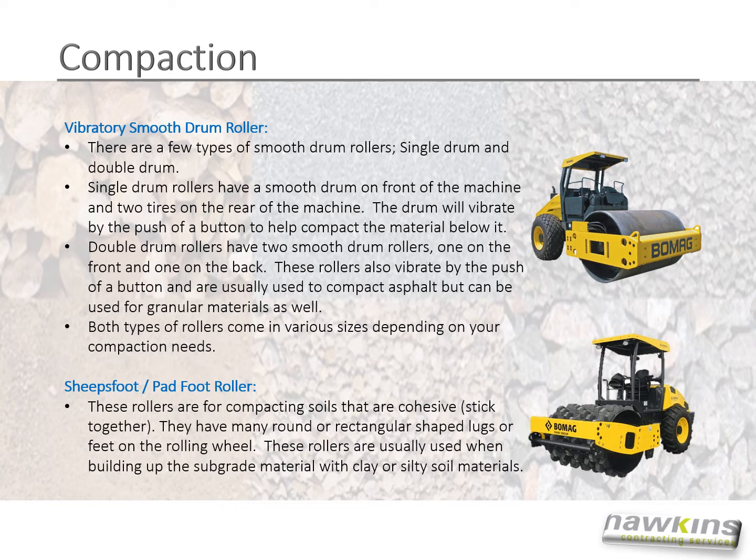Sheep's foot, pad foot roller. These rollers are for compacting soils that are cohesive. They have many round or rectangular shaped lugs or feet on the rolling wheel. These rollers are usually used when building up the subgrade material with clay or silty soil materials.